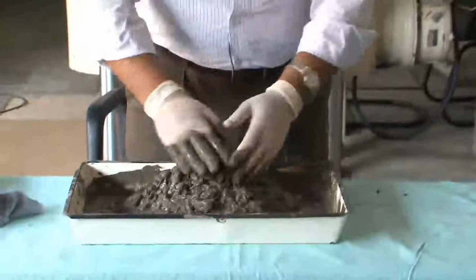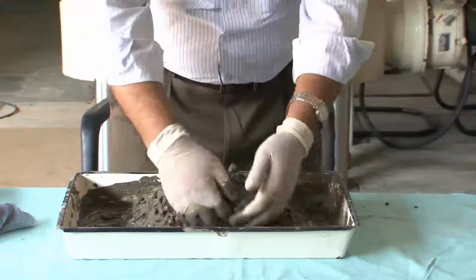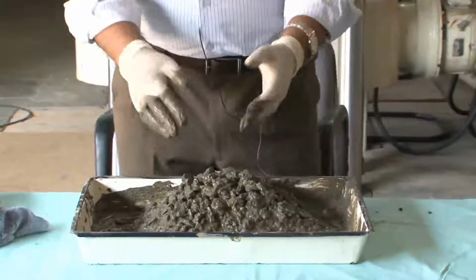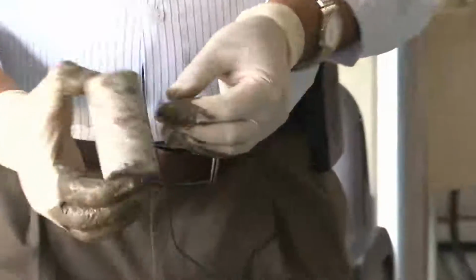So, now this volume of concrete here has been produced using 500 grams of water, 1000 grams of cement, 1.3 kgs or 1300 grams of fine aggregate, and 2600 grams of coarse aggregate. So, this is the concrete which we now have. And finally, if it was allowed to harden, what we will get is a core, which is something like this.